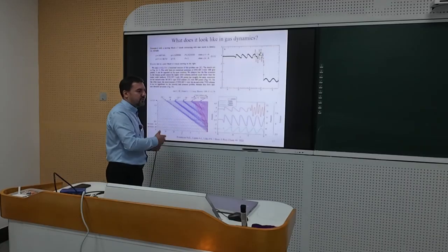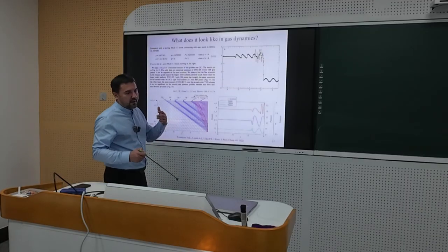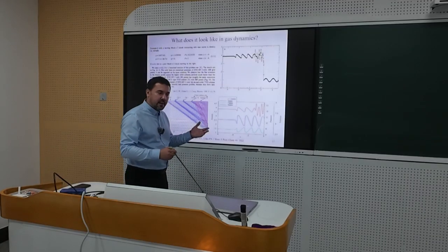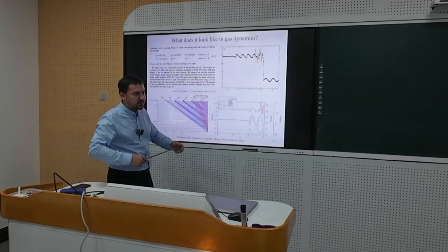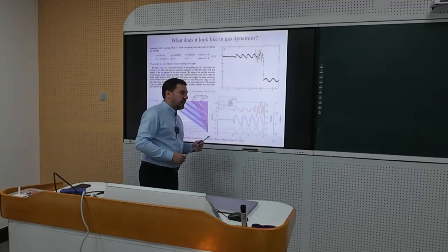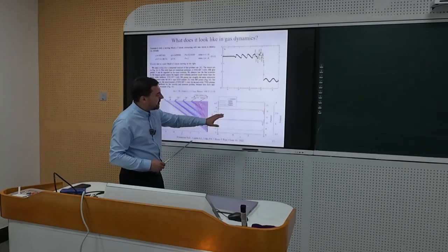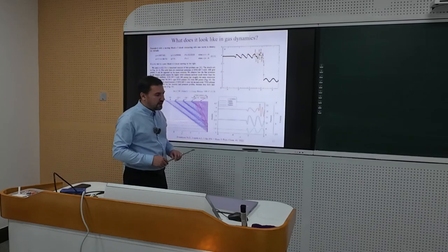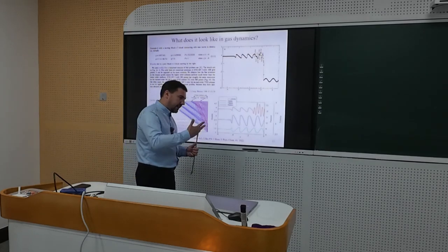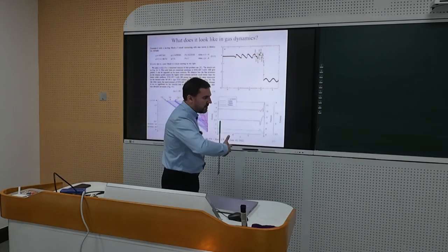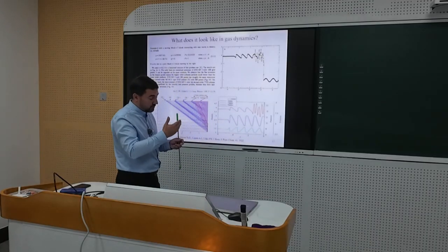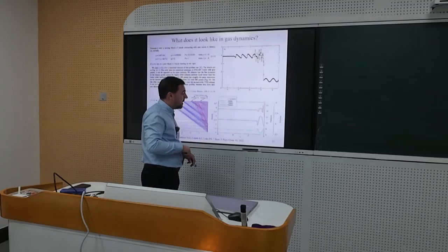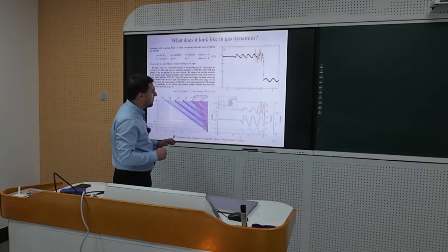I tried to explain to you in the first part of our lecture that analog equations, simplified models are important. So even Euler equations, although they're very difficult, you can try to solve them in 1D. And we solve them not only in 1D, but also in a shock-attached frame. So to study the dynamics of propagation of a wave in complex media, we moved to a reference frame attached to a shock wave. It's a non-inertial reference frame.